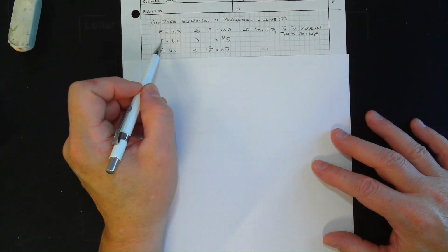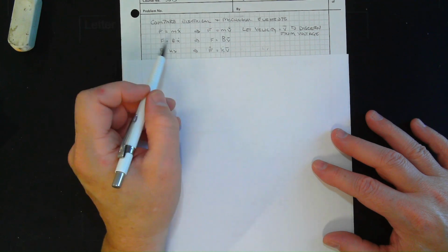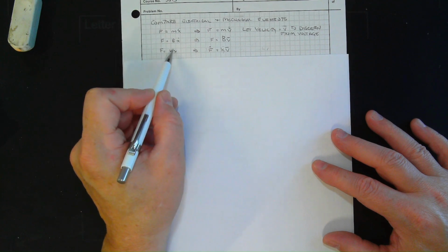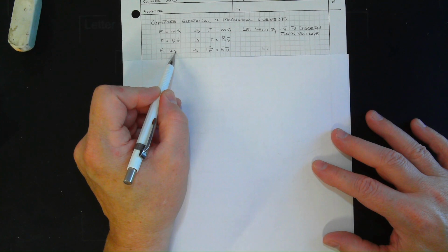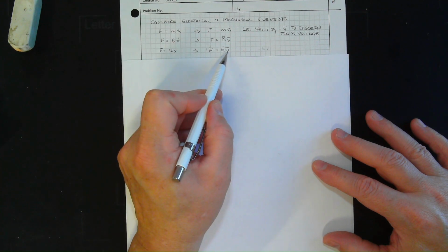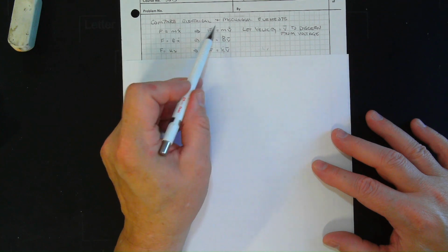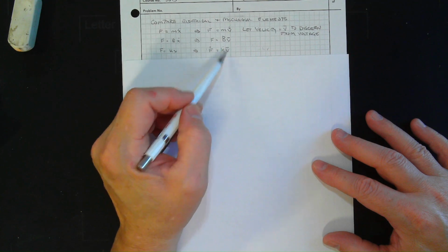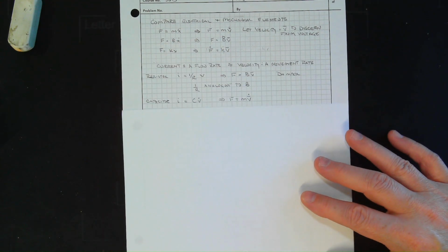On a damper, force equals B times V. So you're used to that. And force equals K times X. Well, if I take the derivative of that position, I'd get velocity, and that will put an F dot here. So I can relate everything in terms of velocity and force.